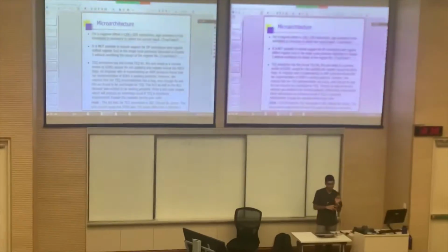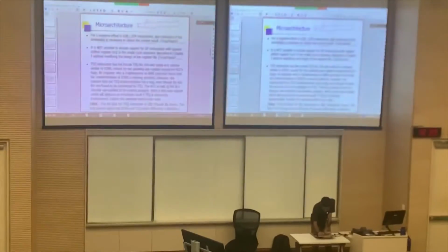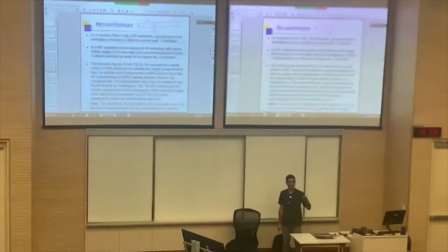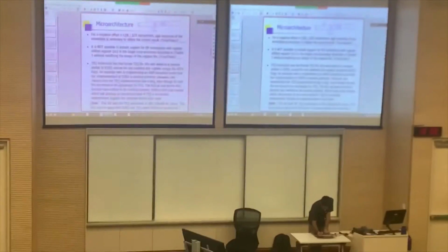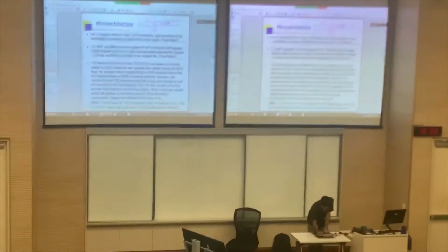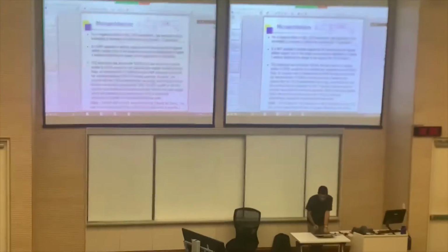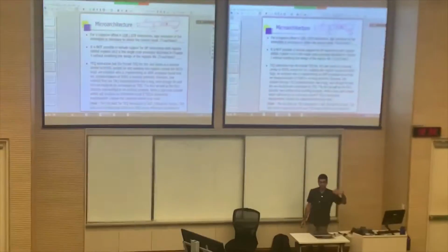In memory instruction format, of course, the first 4 bits are the condition bits, then OP is 0, 1, then you had your func field, of which one of the bits is U bit. If U is equal to 1, it means the immediate is to be added to the base register. Then you have your base register Rn, then the source or destination depending on load or store, Rd, etc., and then finally you have your immediate. So this immediate is added to Rn to find the effective address if U is 1. It is to be subtracted if U is 0.